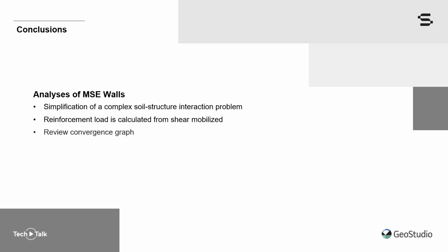It is critical in any slope stability analysis, and especially when reinforcements are involved, to review the factor of safety versus lambda convergence plot because point loads lead to high base normal stresses which manifest in high strength contrasts between adjacent slices. This is the fundamental cause of convergence problems in a limit equilibrium analysis.